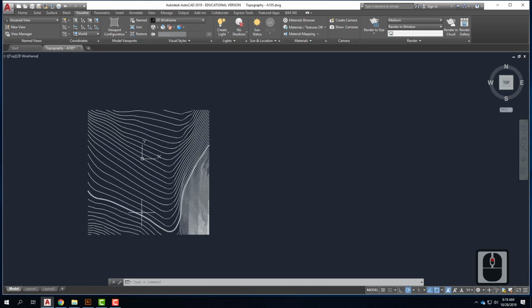These contours are at 1 foot intervals, and they're going downhill as you go toward the top. So this is going downhill here. The river flows right through where all these little arcs are. So it goes right along here, like that. You can see that we have one set of hill where the contours get steeper on this side, and they're much flatter over here. Most people are going to design somewhere in this flat area, right about there.